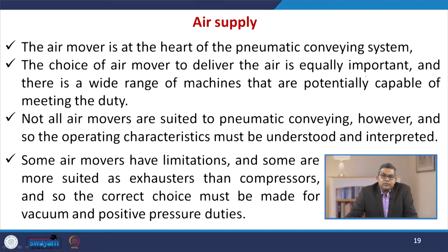However, if the operating characteristics are taken into consideration, they must be understood and interpreted based on knowledge of air supply. Some air movers have severe limitations and some are more suited as exhausters than compressors, so the correct choice must be made for vacuum and positive pressure duties.